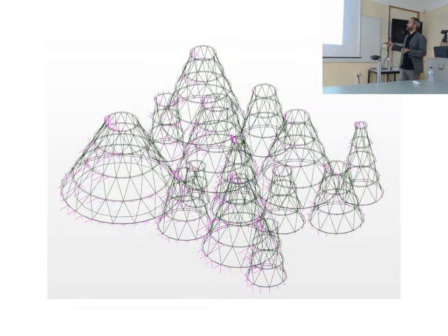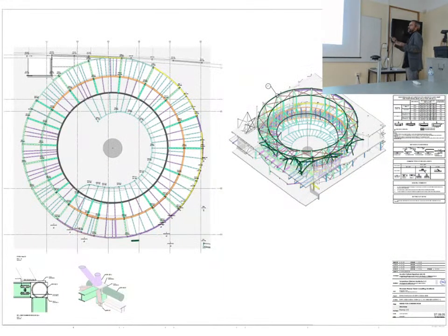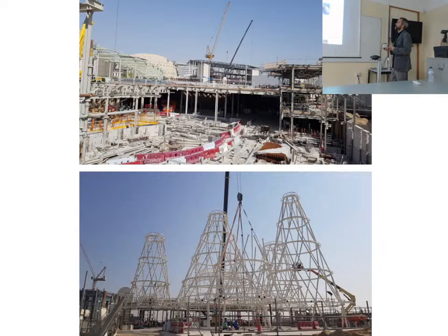So this in pink, you see all these arrows, are the different forces, sometimes tensions, but not in the direction of the wind, in the direction of the reaction of the fabric. You understand? So it was quite tricky to move from the wind tunnel test to the calculation model, but at the end of the day, we have some forces and we designed the steel structure. And this is the geometry of this huge ramp I was mentioning, that was solved with some frames and cantilevers. Some pictures of the construction.